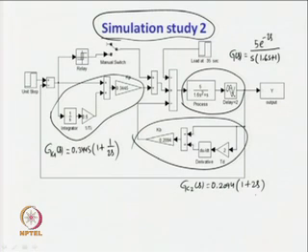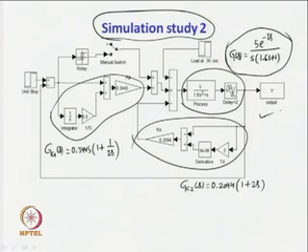Now, the basic objective of having two controllers is that integrating processes are difficult to control, and for getting the desired output, the inner feedback controller is employed. So, with the help of the inner feedback controller, first the dynamics of the open loop integrating process is stabilized, and thereafter the PI controller is applied to get the desired response from the system.